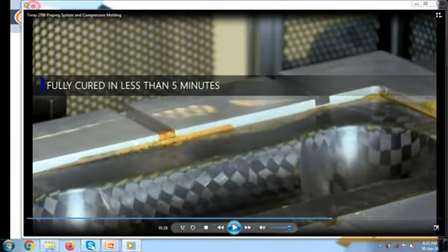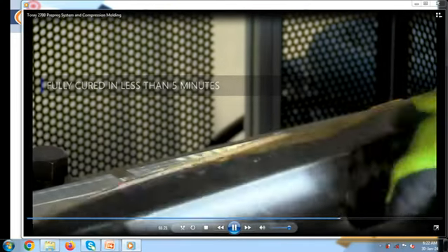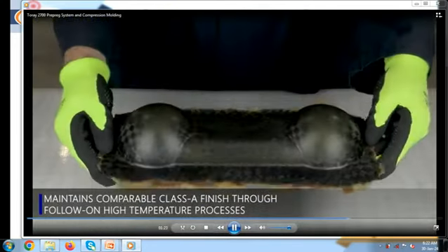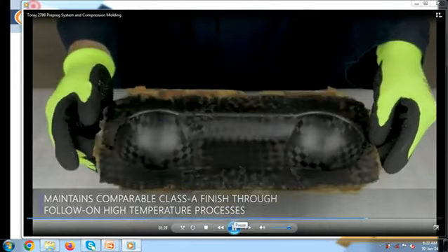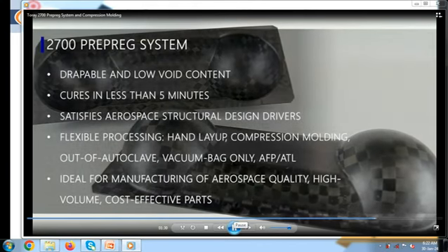Now with the application of load, after 5 minutes we have the required curing period of 5 minutes. After 5 minutes we can see that our mold is ready. Now the only thing is that we need to remove some of the edges and clean the edges, so that finally you can see these kinds of shapes you can achieve with this compression molding process.